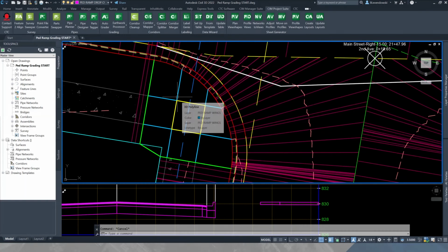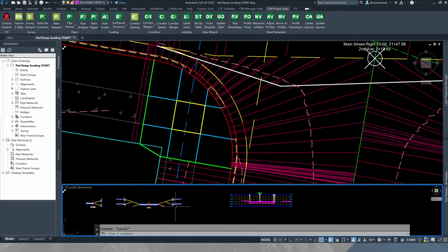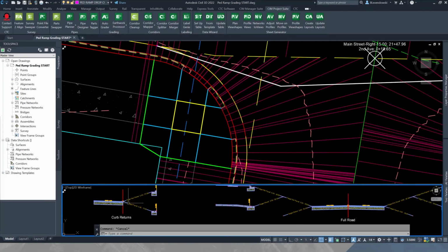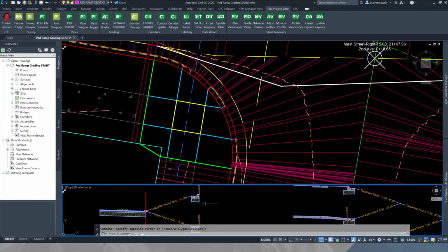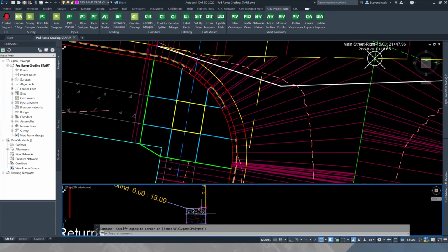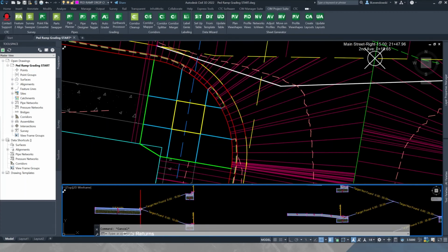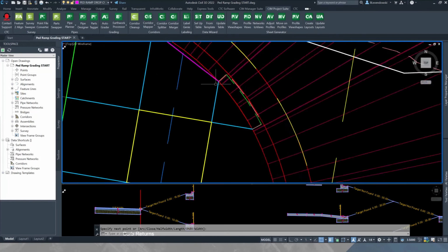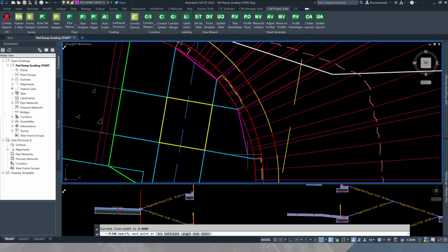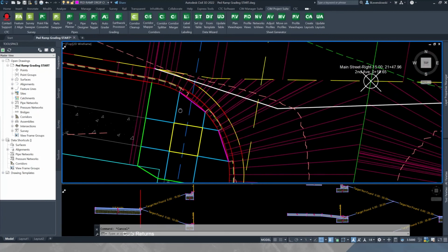All right, there's our geometry. First thing we need to do is get our curves to be flat curves, ped ramps in those areas. So I'm using this subassembly, or assembly rather, in this area. And what I have is a set of conditionals that have either standard curve or full curve, or drop curve rather. Now conditionals work by having targets assigned to them. So what I'm going to do is generate a couple polylines that represent where my drop curve will be.